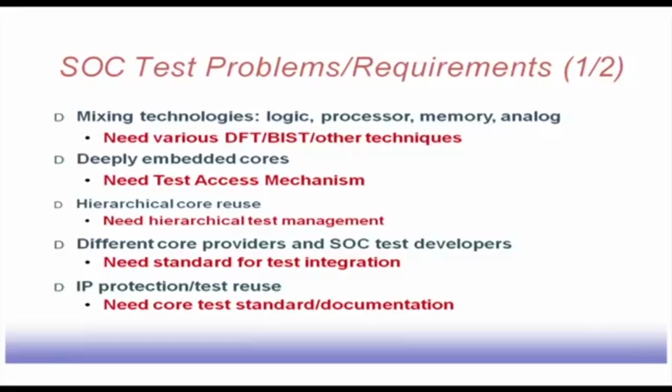So, the requirements change. Unlike a design which is done in house by a single designer, here different core vendors have their own DFT, own BIST and all those things. So, bringing compatibility is a big issue. From the outside world we have to add something extra into the system so that the whole thing becomes compatible and the test sessions can be run.